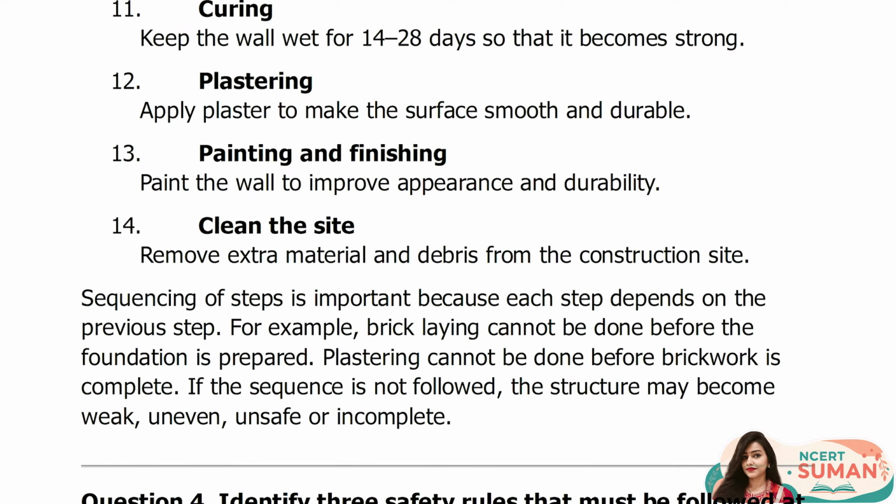Sequencing of steps is important because each step depends on the previous step. For example, bricklaying cannot be done before the foundation is prepared. Plastering cannot be done before brickwork is complete. If the sequence is not followed, the structure may become weak, uneven, unsafe, or incomplete.